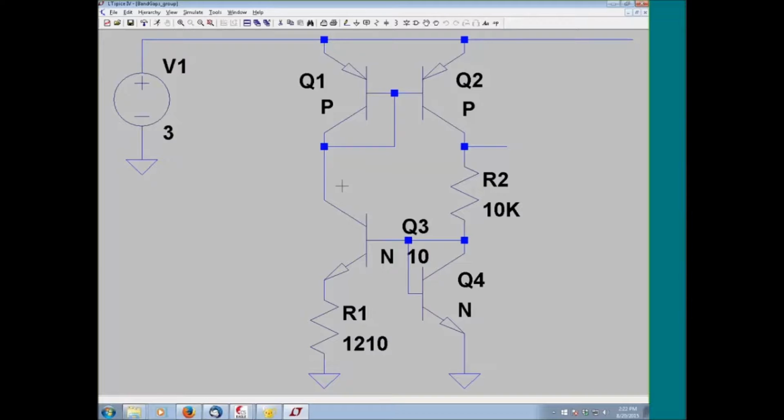Likewise, to bring in something from LTSpice into EAGLE, there needs to be a counterpart. So the key here is always making sure that for whatever you're using within EAGLE, there's an equivalence in LTSpice. If you started in LTSpice and you want to import into EAGLE, there needs to be an equivalence. Without that, you'll find that it's difficult or near impossible to get anything to import. But luckily, the designer of this interface added some provisions to really simplify achieving that correspondence. And that's what we're going to go into now.